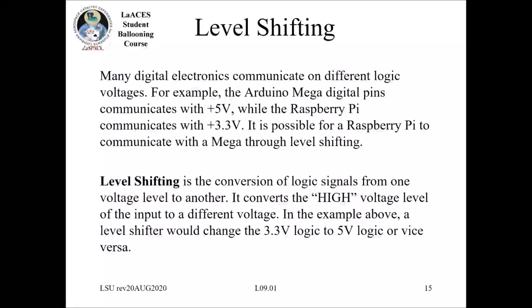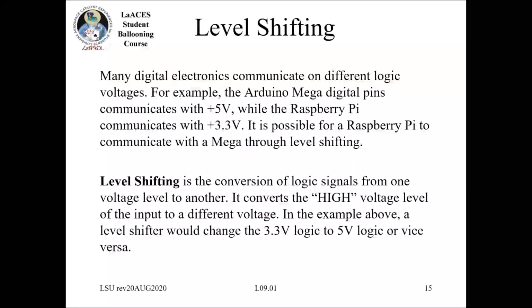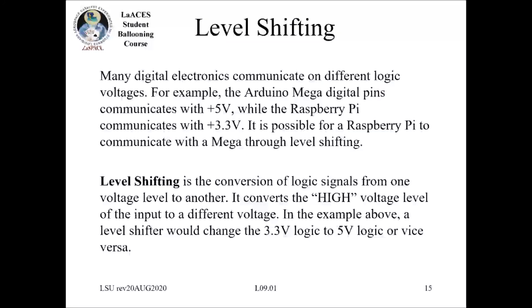I believe at this point you guys should have already gone through some digital I/O programming lectures, and all of those things are 5 volt logic. And if you try to use 5 volt logic on a 3.3 volt or a different one, it's just not going to work.